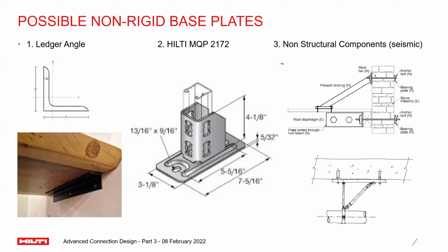There is no textbook definition of when to consider a base plate rigid and when to use a non-rigid approach. So this is where the experience of the user comes in handy. An experienced engineer is more likely to be a better judge of whether to use the rigid versus the non-rigid base plate design approach.